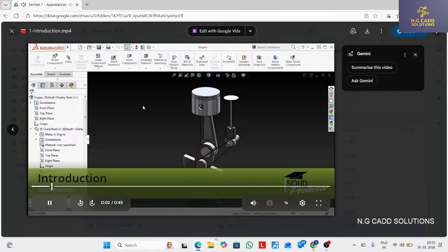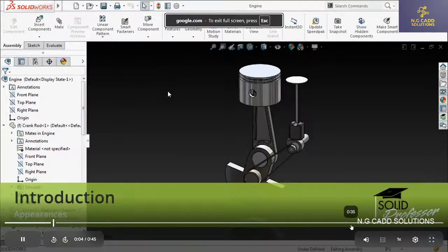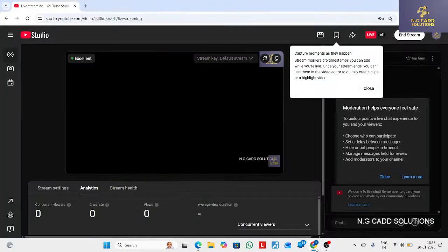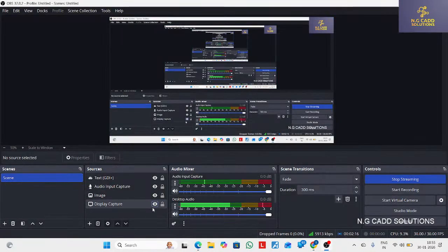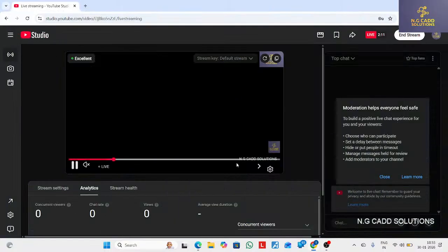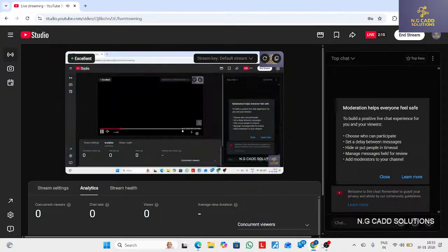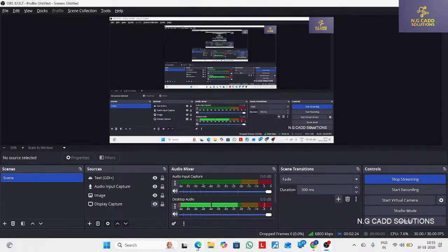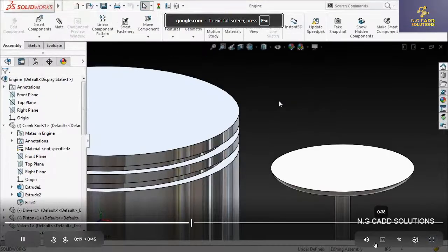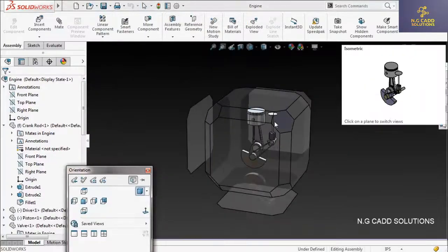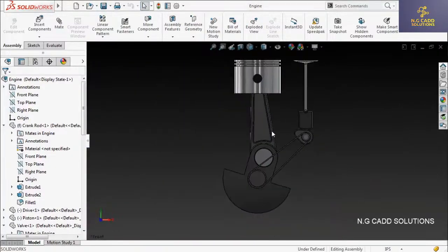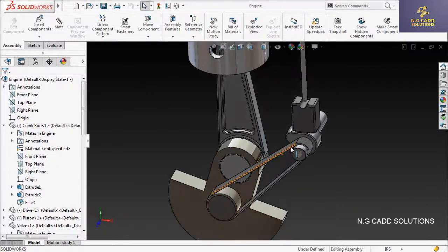In this section, we'll take a look at an important element of giving your models a more realistic look: their appearances. Appearances are material files used in SOLIDWORKS that specify surface properties on a model. These surface properties include color, texture, reflectance, and transparency. By using the Appearances editor, each of these properties can be modified and edited to get the desired effect on a model. There are two types of appearances: procedural and textural.